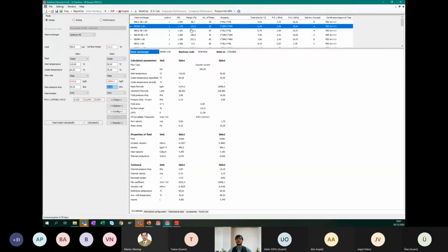That creates, together with the impact of very high mean logarithmic temperature difference, which is 21 degrees, that's actually considered to be high LMTD. We usually say it's high if it's above 10. It's medium from 10 to 5. It's low if it's lower than 5.